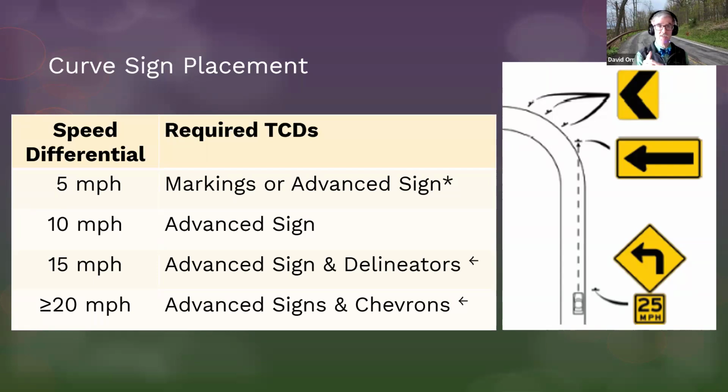The biggest challenge there is being consistent. Do you have a policy or do you have at least a thought process of when we're going to switch? You know, if we've got 85th percentile information that says the difference speed is more than, say, 10 miles an hour, probably okay. But think about that. Think about what would happen if you wound up in court.